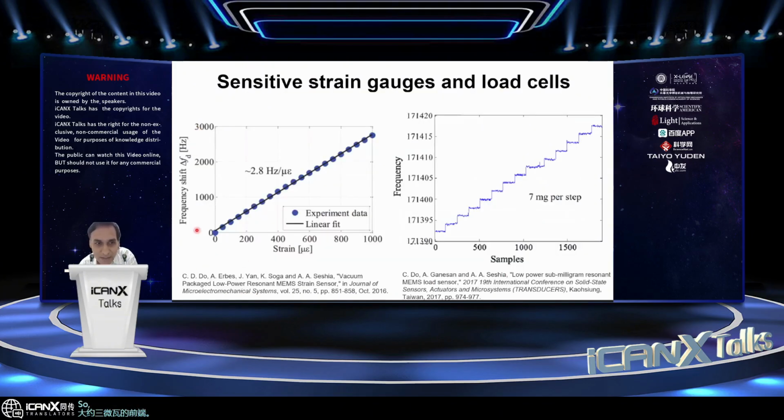So the measurements from that are shown here. One of the advantages you see here is the very large dynamic range. That comes with this frequency output principle. So you get excellent resolutions well below the nanostrain, very high sensitivities, as I said, that enable that, but also the very high dynamic range with a very good linearity, even though the fundamental principle itself is nonlinear. But over this large strain range, you're still pretty linear.